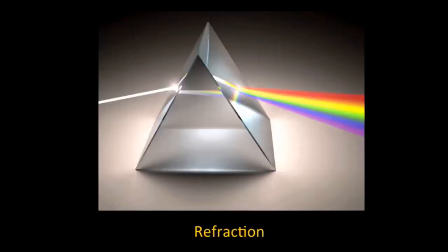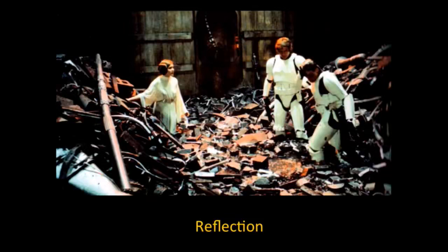Okay. Other things that affect wireless, you've probably all seen the light bending through a prism. We have waves that are refracted as they move through different sources of interference. So we're propagating through different wall types as they move through the plaster, if it's a steel-studded wall or a wood-studded wall. A lot of offices now have floor-to-ceiling glass walls. And so this has significant impacts on the way waves propagate through glass-based mediums. Outside walls are coated to prevent solar energy from coming in to help keep the workspace cooler. They also provide significant attenuation for walls. And we know Han Solo learned an important lesson in reflection in Star Wars when he fired his blaster in the trash compactor, and the blast bounced back and forth off the walls, almost hitting Luke and Leia.